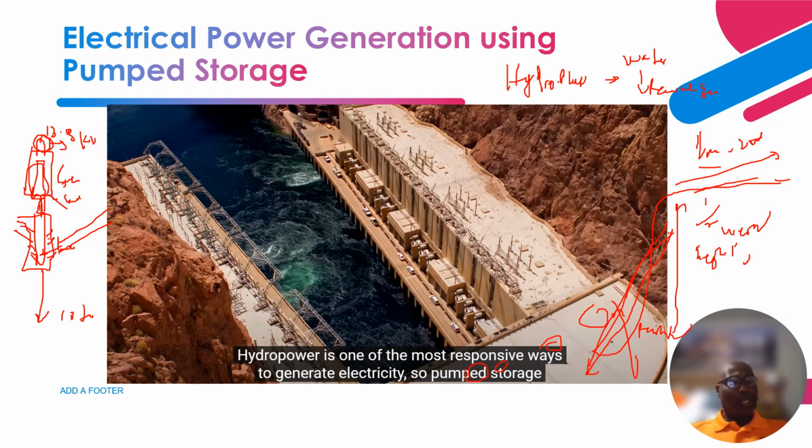These turbine generators for hydro are very slow. They turn very slowly because they are what they call salient pole machines. The rotor has poles wound around it, comparable to cylindrical rotor machines that turn at a faster revolutions per minute, about 1800 or 3600 RPM.